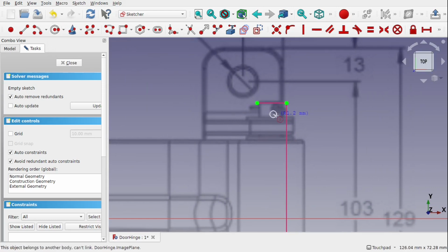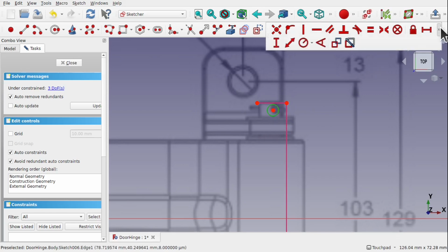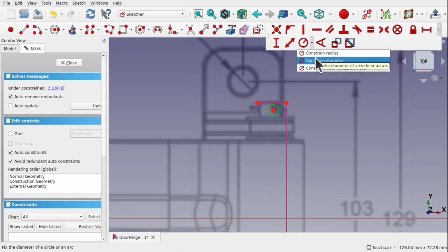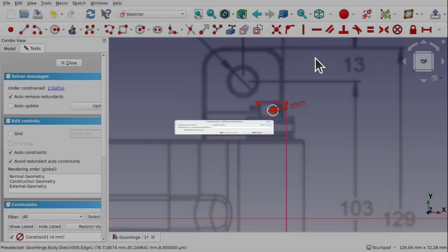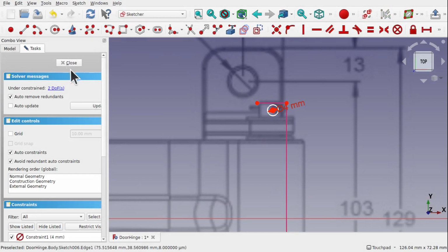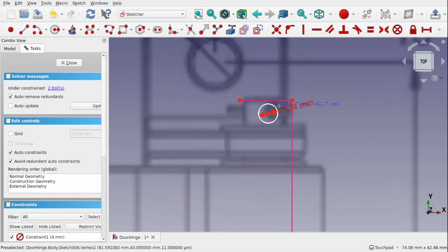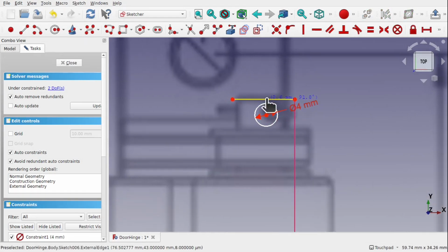So I'm going to place a hole around about here. I may push this a bit forward as well, because at the moment this is quite close. I want a decent sized hole to take a pin. Let's go for 4mm, and we'll place a line. Going to start at this point with this line,